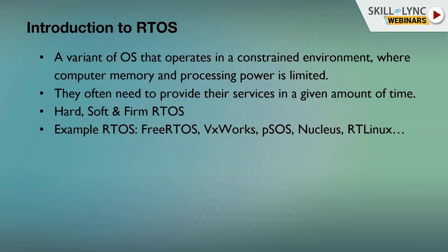So if an event has to happen in 0.2 seconds in this particular scenario, it has to happen at that 0.2 second. There is no delay accepted. There is no lag that can be accepted in these particular scenarios. Those systems are called hard real-time systems, where a lag of even 0.1 seconds cannot be accepted, as it is a critical event. So we have to prepare our real-time operating systems as hard real-time operating systems.